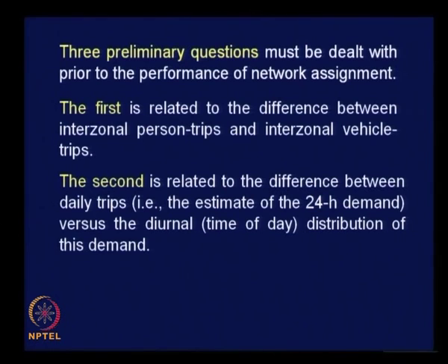The second is related to the difference between daily trips, that is the estimate of the 24-hour demand, versus the diurnal time of day distribution of this demand. Again, please note, when we talked about trips in trip generation, mode choice and trip distribution, those trips are related to daily trips, total of all the trips made for a 24-hour period on a typical working day.